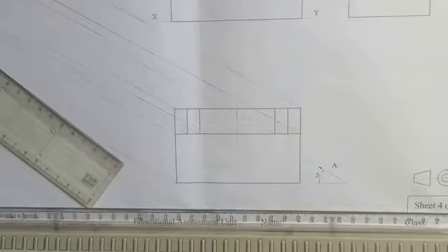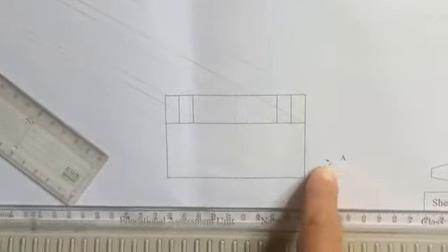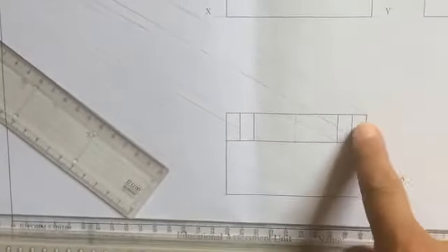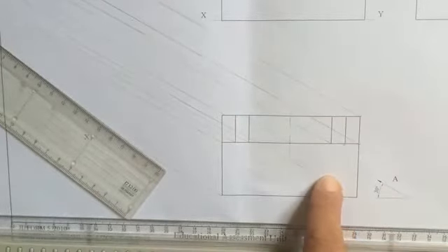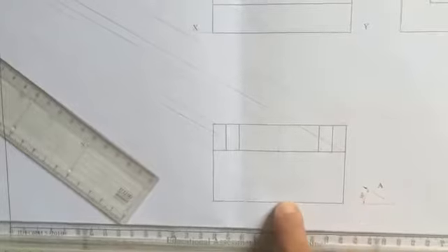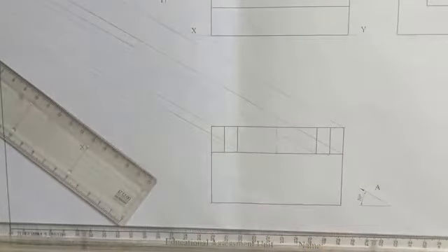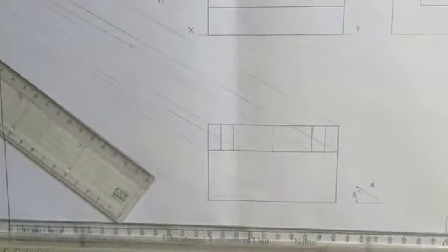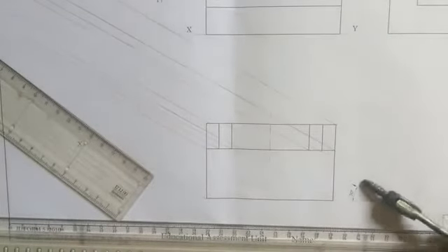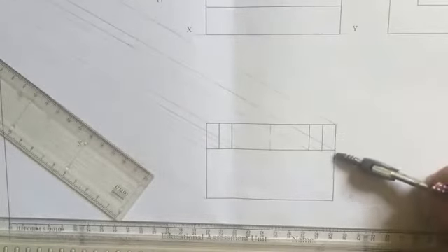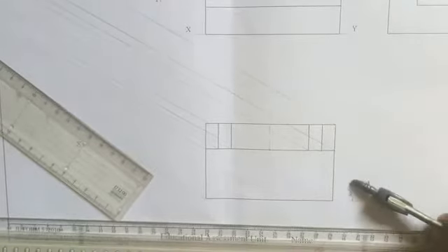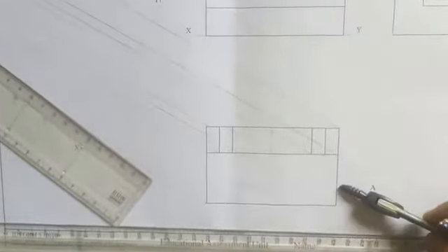Thanks for listening. So what I've done here, I've drawn some projection lines at this angle, at 30 degrees, onto the given XY line. Right? Now, sometimes I suggest not to draw the projection lines at once, just draw a face at a time, so as not to get confused with all the lines. Now I'm looking at it from this side, so I'm going to start from this face here, the one I'm looking at, because that's the most visible side.